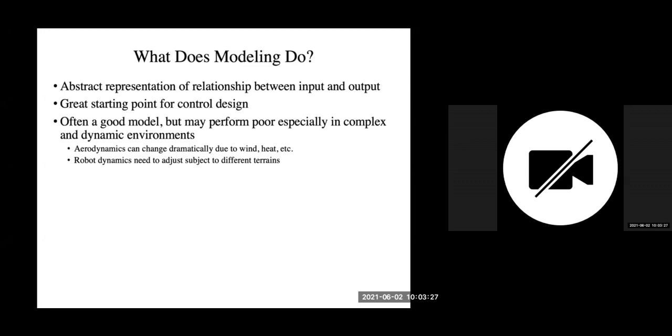That's exactly what happens when you do navigation, for example, starting from A to B. We want to know exactly if you take action, the robot will behave in a certain way, and we'll see the output will tell us if it's moving towards the goal or not moving to the goal. Especially when we talk about path planning, because if we plan the path for the robot to take, and we take action, we can compare if the actual robot behavior will match the path we actually planned. If it does match, which means we can continue. If not, we need to adjust the control inputs, or the algorithms.